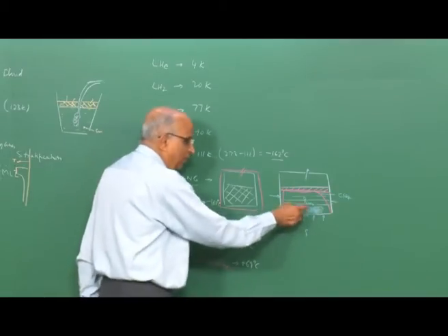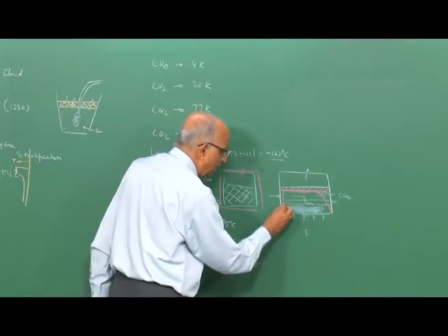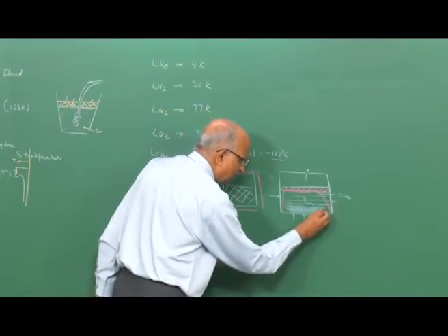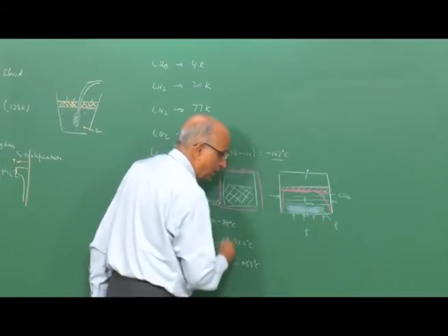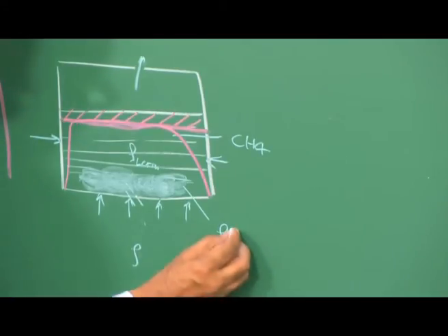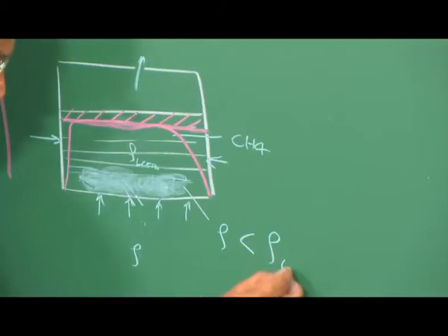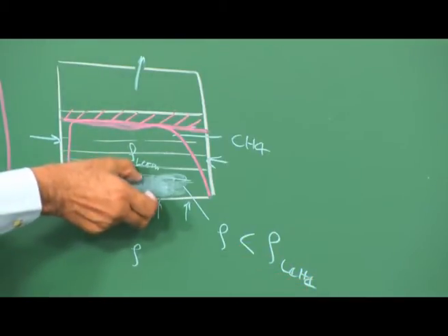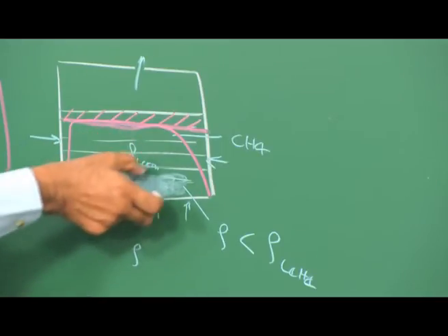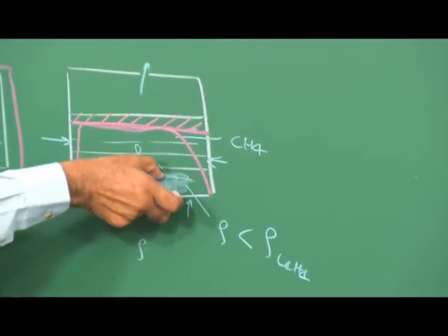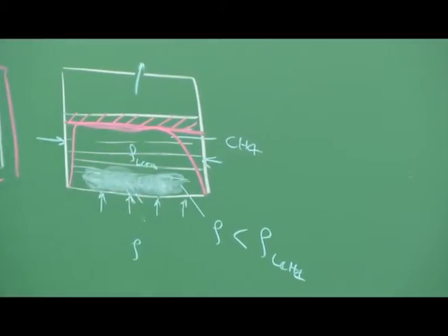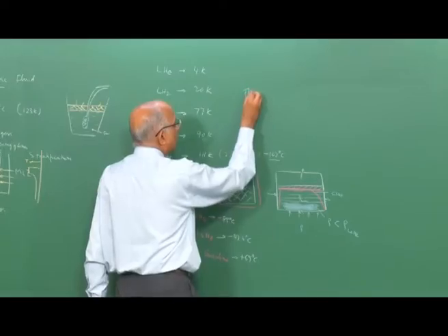And therefore, it continues to get heated till a particular time when the liquid density of the corresponding heavier constituents becomes less than that of the liquid methane, and you have higher energy or higher temperature over here. This layer of heated heavier constituents is known as thermal overfill.